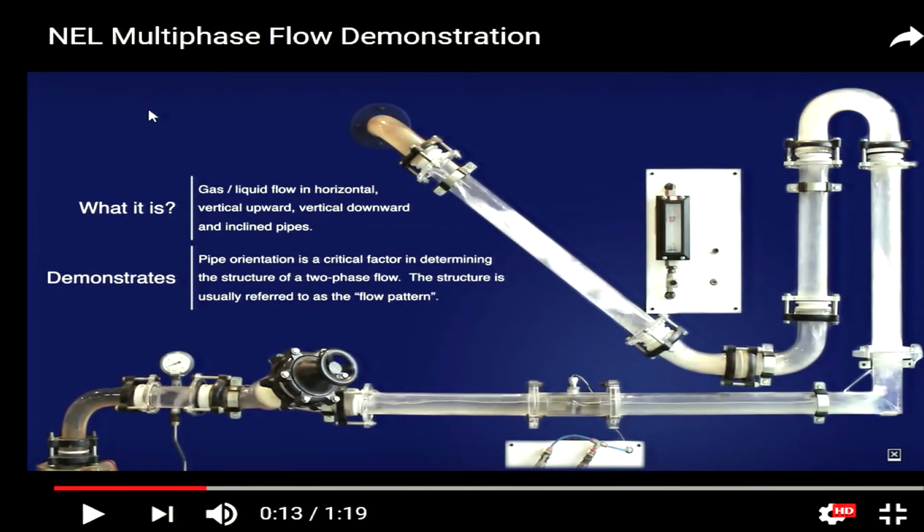Okay, so let us pause for a second. You can see very nicely the bubbly flow regime, and it is almost homogeneous. The bubbles are almost homogeneously distributed in the whole cross section of the pipe, whereas in the bottom you can see it is sort of a separated flow, right. And then here it is a mix of one part bubbly flow and the other part stratified. I mean, you have a mixture of bubbly flow and stratified flow when it is going down essentially.